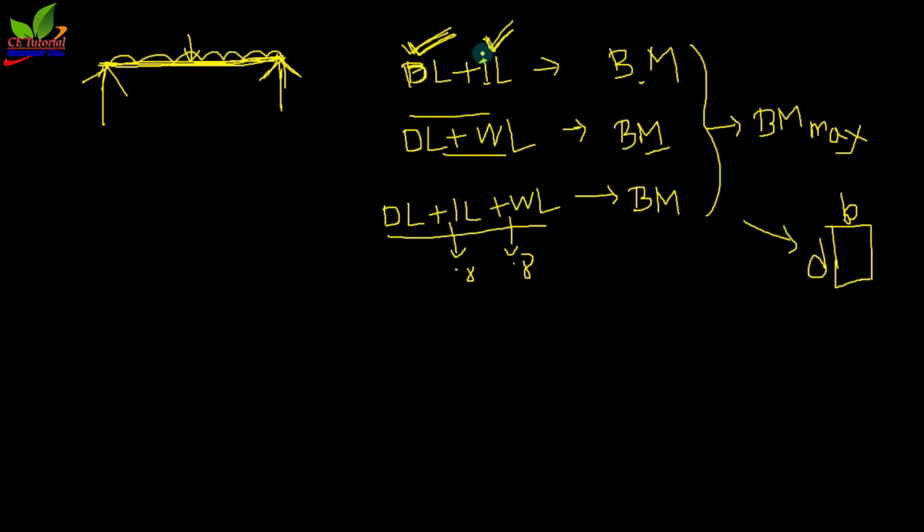If it is a commercial building, there is a certain rule in IS 875 part 2 for what the imposed load should be. If this is a residential building, there is also a guideline in IS 875 part 2 for imposed load. So you have to follow IS 875 also.